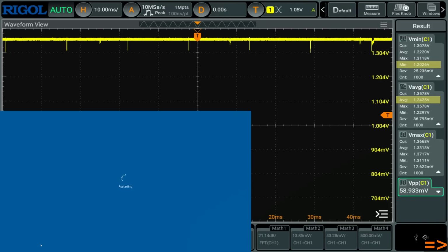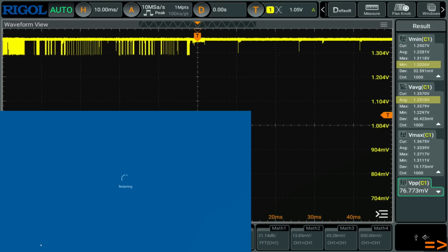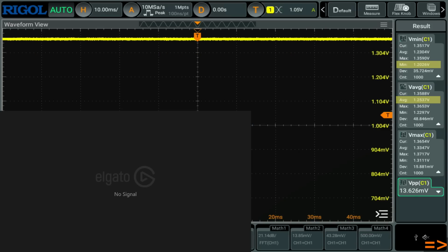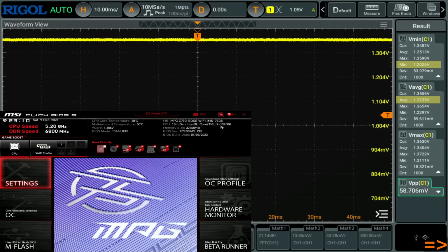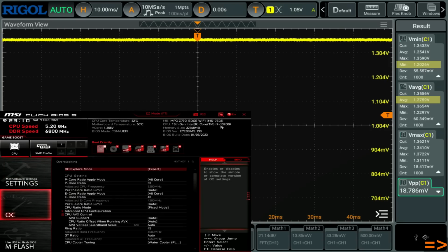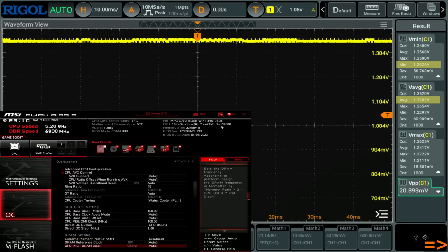And this is the other reason I really wish, imagine if mode 7 and 8, instead of having an 80 millivolt gap between them, had a 40 millivolt gap, right? And then mode 6 was what mode 7 is right now. So mode 7 would be like 1.42 volts, which would get us very close to the voltage regulation that we're probably going to see with mode 8, and we'd have even less undershoot than we already have. Right now, mode 7 is pretty good. It's not perfect, but it is pretty good.